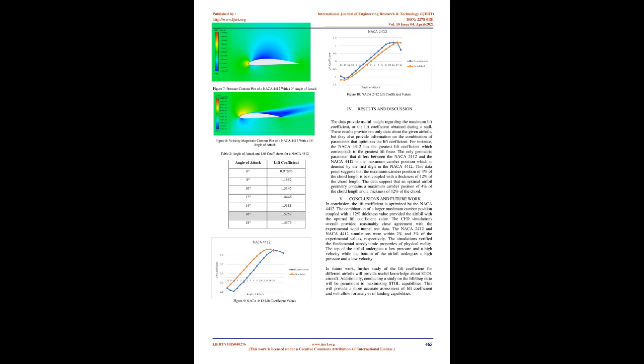This paper's primary focus is the lift coefficient, so I will be using a velocity comparable to a reasonable takeoff speed of 20 m/s, or around 40 knots. The components of the fluid flow velocity are varied in order to obtain different angles of attack. For instance, to simulate a 6 degrees angle of attack, the x and y components of the fluid flow velocity are 20 cos 6 degrees and 20 sin 6 degrees, respectively.